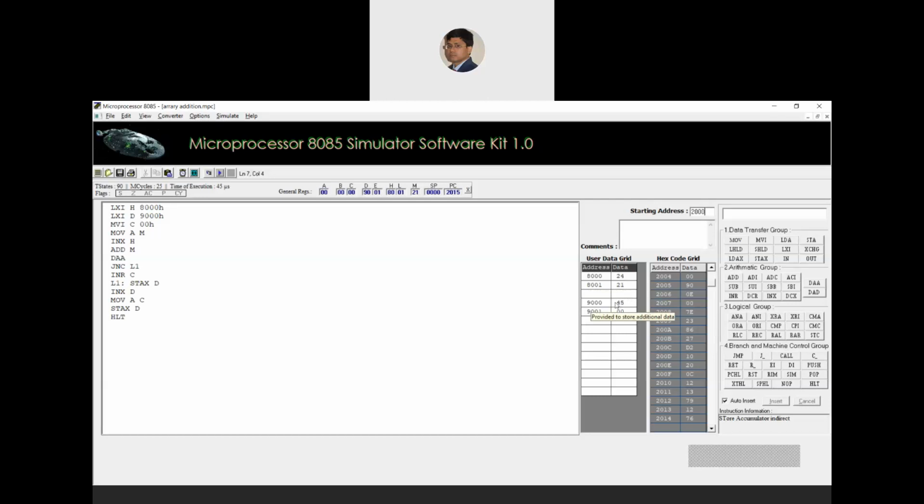So 45 is such a number where there is no carry flag and no auxiliary carry flag after addition. Not only is the lower nibble not in the range of A to F, but the upper nibble is not either. So you understand, this is the simplest example for the addition of two decimal numbers where no conditions are satisfied for the DAA instruction to add 06 or 60.